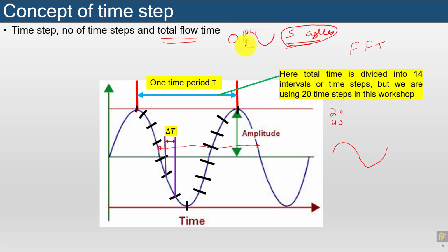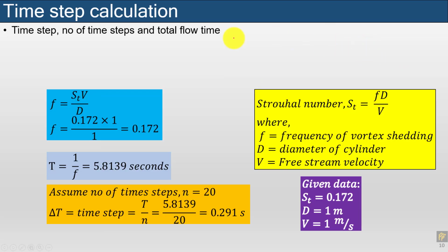So the change in y velocity is going to give you an idea about the largest, dominant frequency in the flow. That frequency we will find from the application of the fast Fourier transform, and this is given inside Fluent. Okay, so now from here